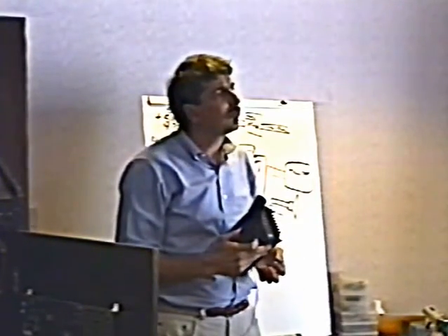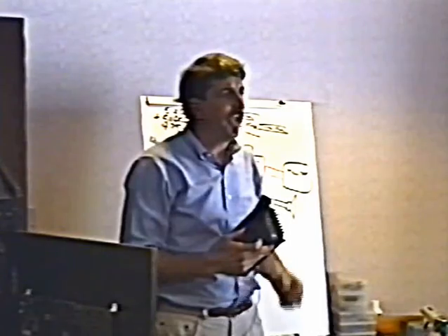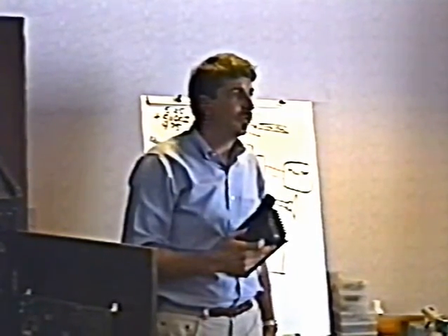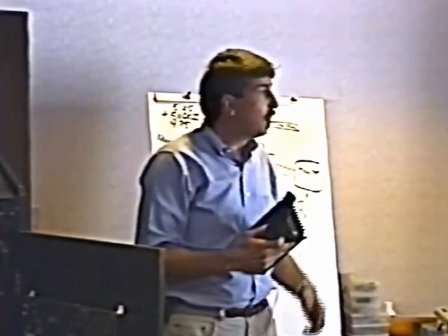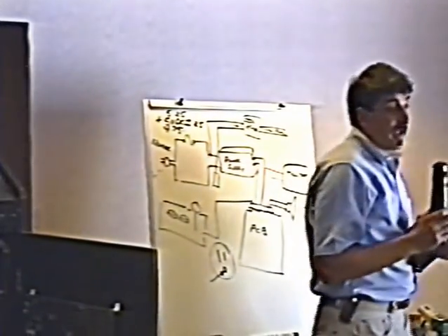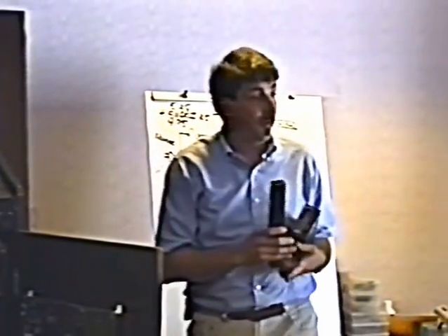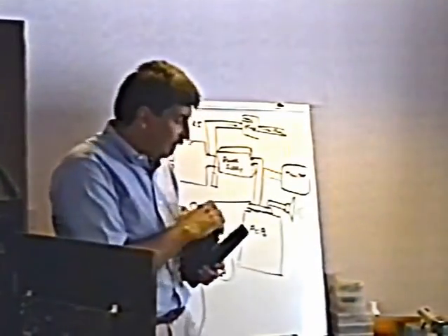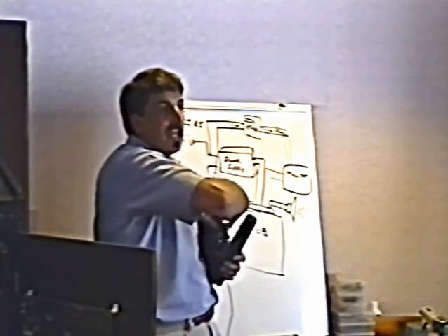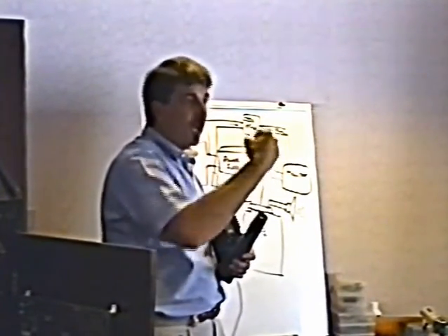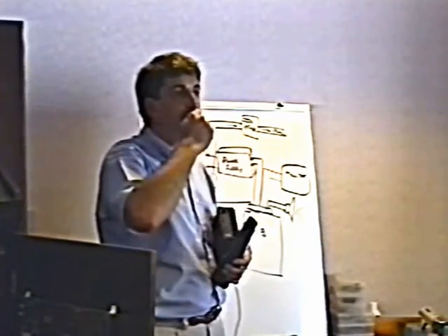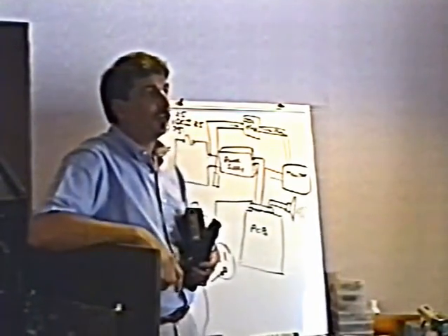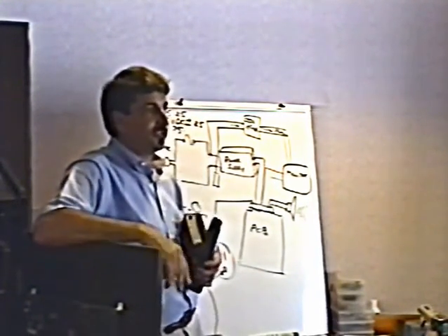So it might be good to unplug it and do it, plug it in and see what you got. No, you can't adjust it when it's unplugged. I mean, I could unplug it off the board and do it and then put it on. No, because, and that comes back to what Howard was mentioning earlier, and I'll amplify this tomorrow. In order to adequately test the power supply, it must have a load on it. You must be sucking current out of it. Again, after I stick it back on and see how it is. No, don't do that. Leave it all connected. Just adjust it with the power turned on.